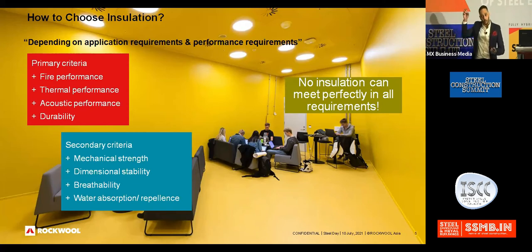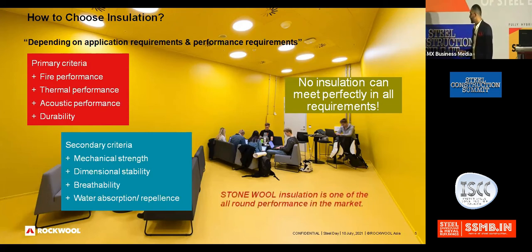Break the sample, put water on the fibers which are inside, no water is going to get inside, because water repellency is directly connected to the thermal performance. 1% of moisture absorption, 25% reduction in the thermal performance. So you need to be very, very sure about the water repellency of the insulation that you are choosing. As I mentioned, Stonewool insulation has an all-round performance to satisfy all the primary as well as secondary criteria.